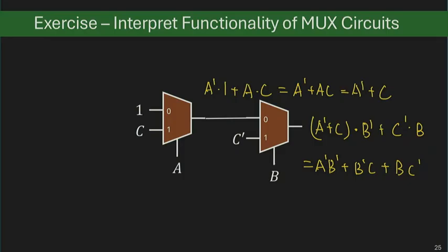All right. Essentially, the idea is to use the selection variable and then complement the inputs on 0 and 1 side with non-complemented and complemented selection variable respectively. This is a Boolean way or algebraic way to construct the output function of a mux. All right, yeah. Any questions about this?